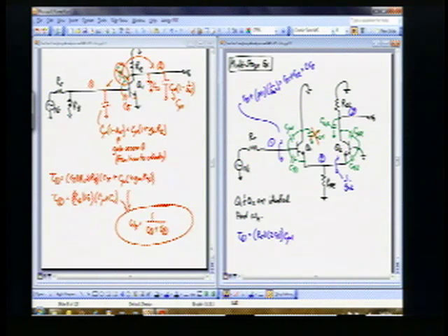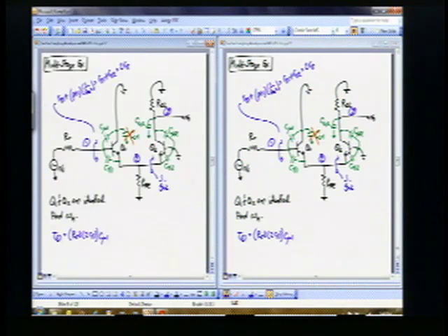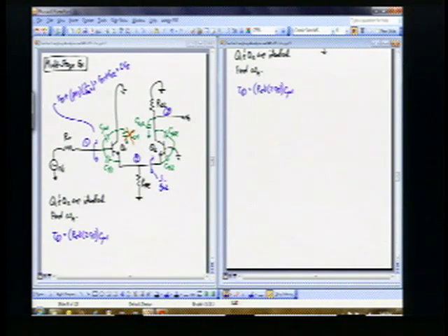So I could see that I have a C pi 1 here. Okay? So with that C pi 1, what's the driving point resistance across that C pi 1? It's going to have a time constant associated, which I'll call tau pi 1. So I'm going to have to take C pi 1 times something there. Okay, so that's not as easy because, again, that's not going to ground. It's not a capacitor going to ground. It's a capacitor going from one terminal to another terminal there.